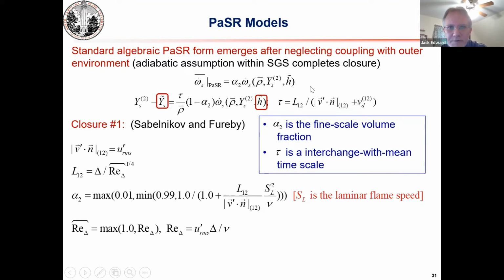So your closure for the subgrid is this, but you have to solve this balance equation at the subgrid level to get the data to push into your closure model. Now, the balance equation is shown here. What I'm highlighting with the boxes are the data that you're giving to it as the truth. This is what's driving the solution. So there are some differences in, for example, MRA, in how you wish to compute these terms.